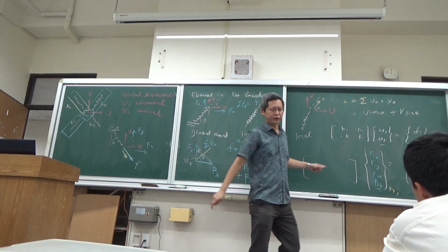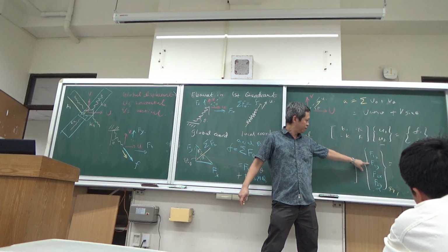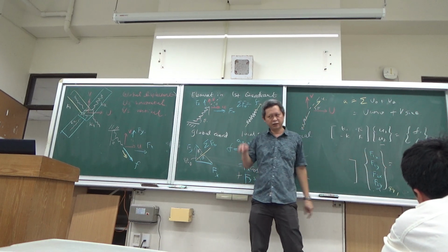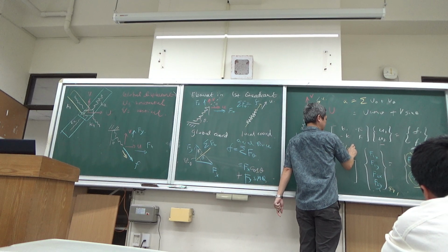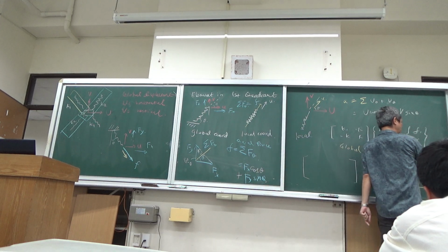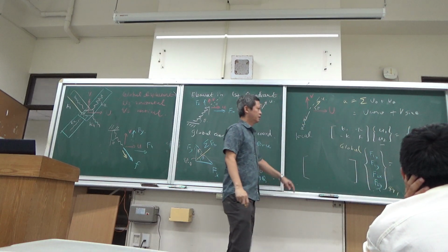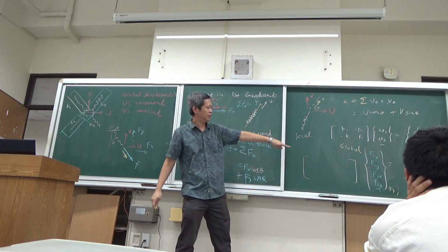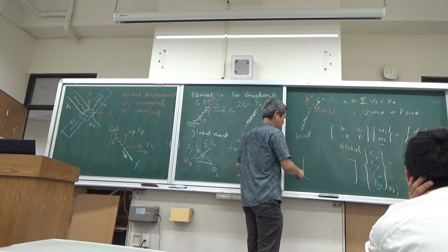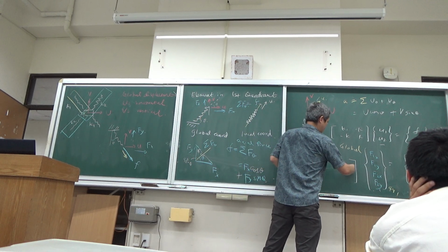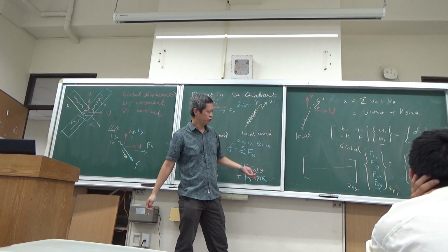So the matrix turns these normal forces into the axial forces. This is the global, and this is the local. Local means axial. So you have to pre-multiply them by a matrix. This matrix is a 2 by 4 matrix. It has 2 rows.